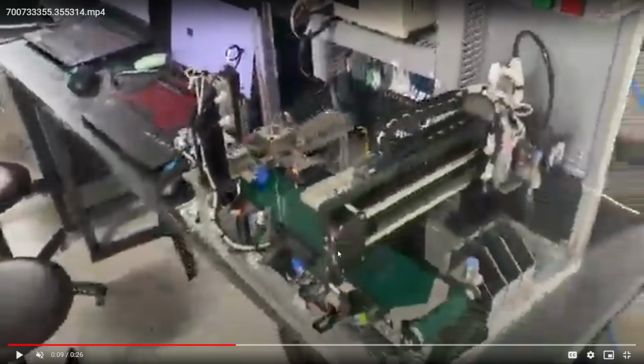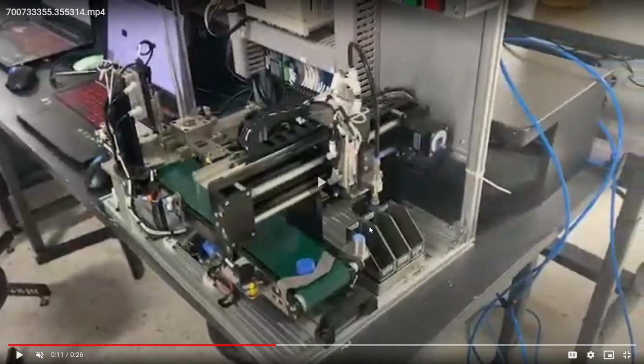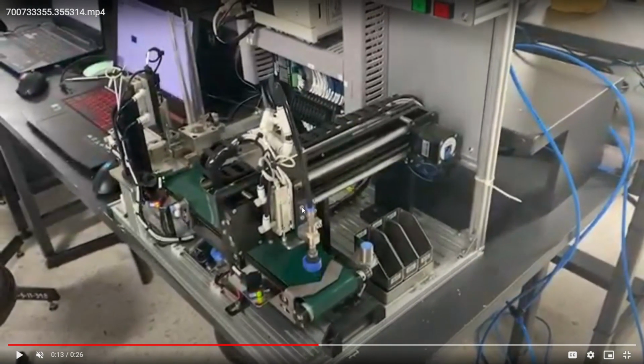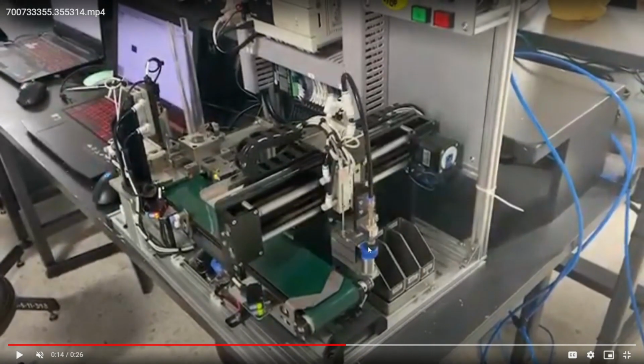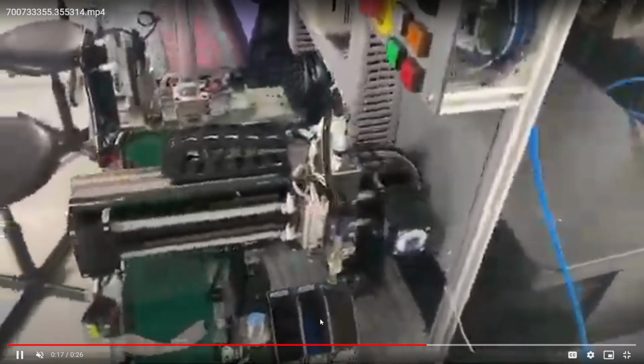Sorry for the blurriness. And you see that when it has checked already, the kicker will kick onto the conveyor, and if it has a hole, it will be pushed down from the conveyor by this pressurized gas, but because it is plain, it continues to the end of the conveyor, and we see that the nozzle is also up and it moves to position 1 and goes down, picks it up, checks for metal, and we have a delay, and then the plastic goes down here.